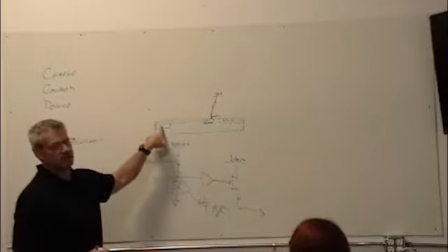Once you've done that, you've still got the issue of this blocking light. If you want to get really fancy, really good, you will then come back and cut this off all the way down to that P++, and then you'll mount them upside down. And now it's backside illuminated.